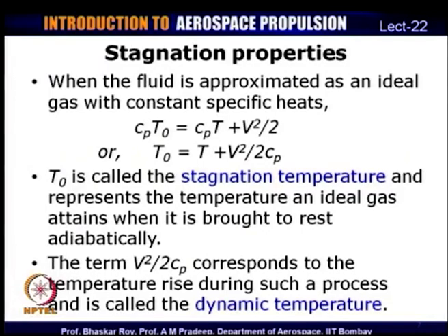That is, as you bring a fluid to rest, the energy gets transformed into internal energy and so on, which ultimately leads to an increase in its temperature and pressure, which we have now defined as stagnation temperature and pressure. This has to be higher than the static temperature, because it has an additional energy term, which is the dynamic temperature term.